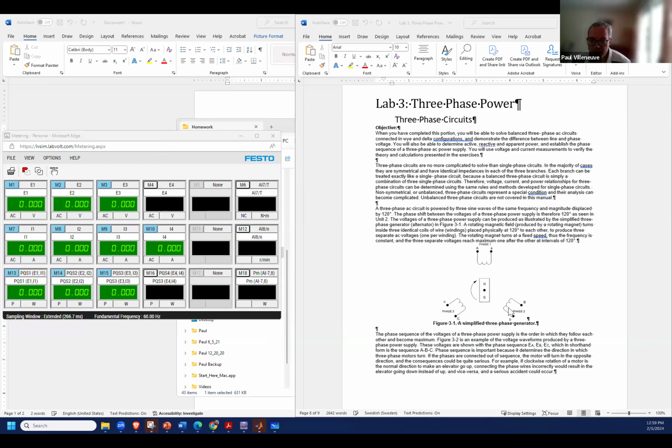And that's going to happen 120 degrees behind or ahead of phase two, which is going to happen ahead or behind of phase three. So the way that you get 120 degrees of electrical separation in a really simple physical world is you just physically rotate the windings and space them out the equivalent of 120 degrees. So that's what AC machines are constructed on.